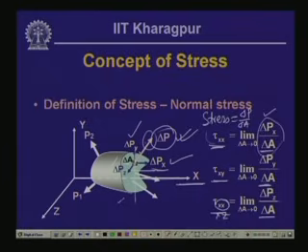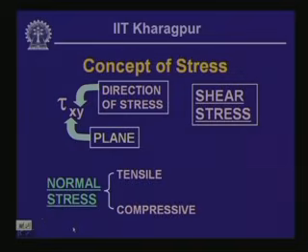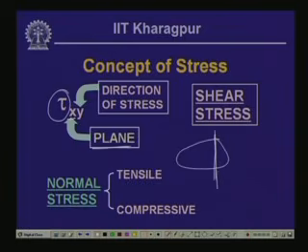Now, on a limiting scale, because we are concerned about stress, when we talk about stress, it is stress at a point. So, the stress at a point, when delta A tends to 0, is given by tau xx, tau xy and tau xz. Now, the way we have given these designations, tau is the term for the stress. The first subscript defines the plane. As I said, for the body we have taken a cut, and the normal drawn to this plane is directed along the axis x.